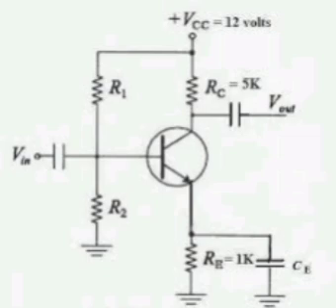The battery EMF is 1.5 to 15 volts, and the full scale current of the meter may vary from 0.25 milliamperes to 1 ampere or even more. Thus R1 will vary widely. Usually R1 is considerably larger than Rm. Then R1 plus Rm equal to R1. Substituting this in equation 3 gives RH equal to Rm.